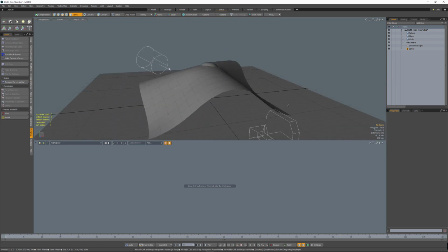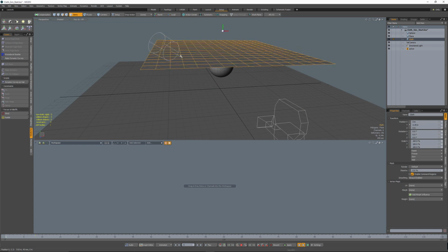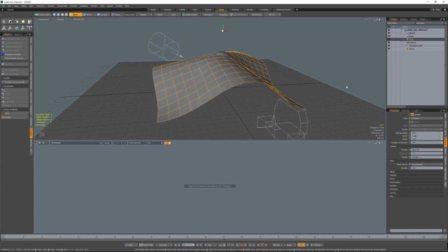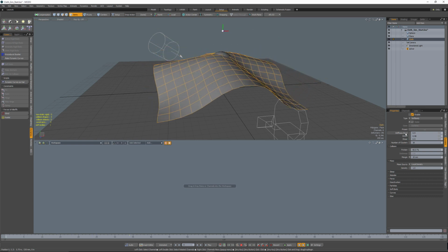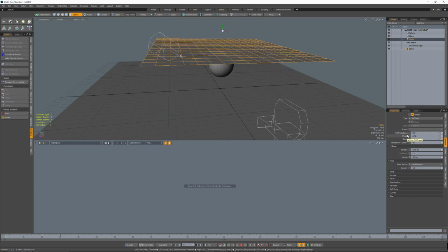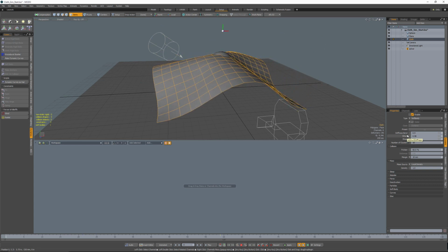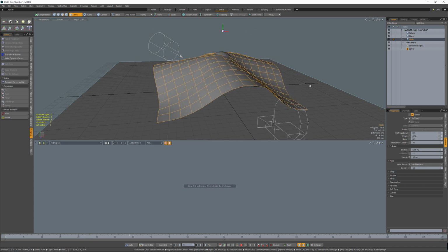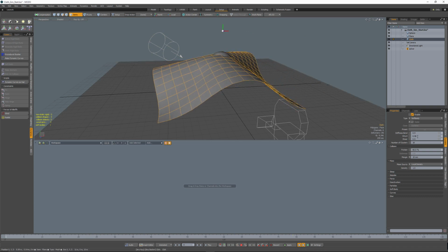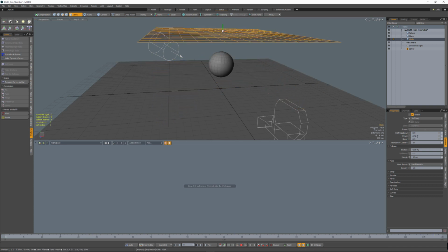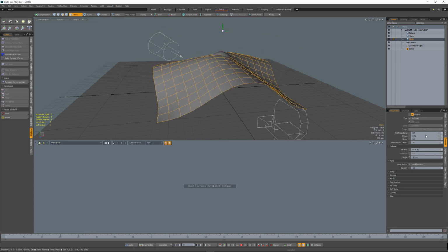All right, so as this plays back, what I'm going to do is actually select this, and let's look at some of the options that we have here when we're working with soft bodies. Now, this stuff is also going to apply to closed soft bodies, so things that are more like a closed mesh. Here we're dealing with a simple sheet, a simple piece of cloth, but these will also apply to closed soft bodies, which we will look at in another episode.